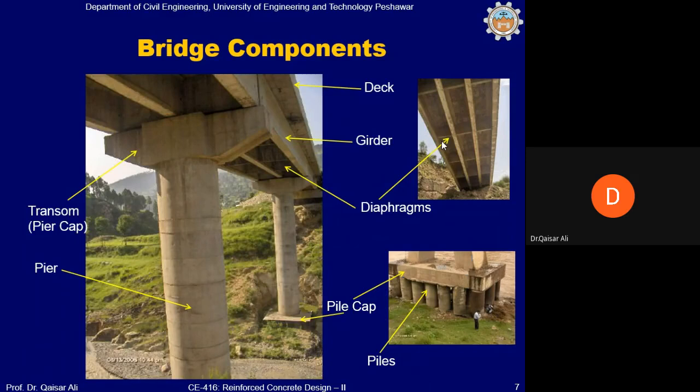This is one reason, and the other reason is that usually the girders provided in a bridge system are very deep, and they are only connected at the top by the slab. So in order to connect them also through the depth of the girder, to increase the even distribution of the load, and also to avoid any buckling along the depth of the girders. These diaphragms are usually called beam diaphragms, and the slab which connects the bridge at the top is called the slab or deck diaphragm.